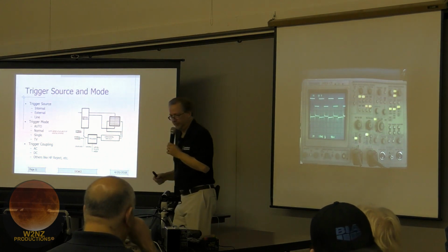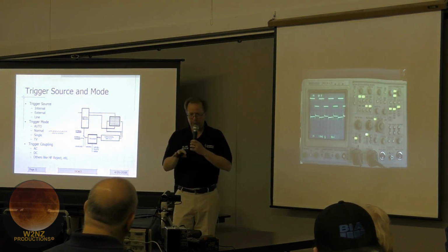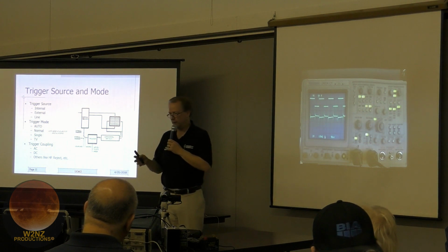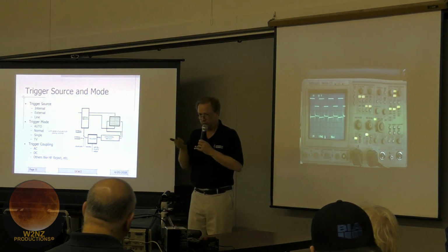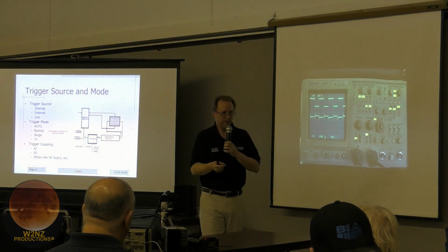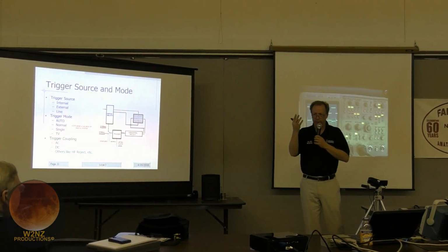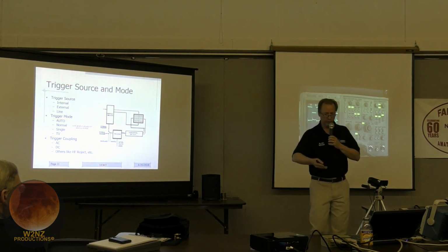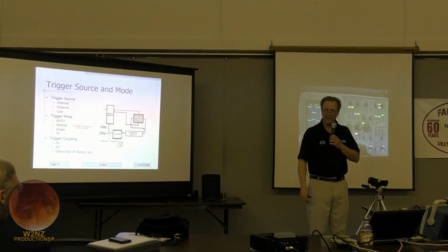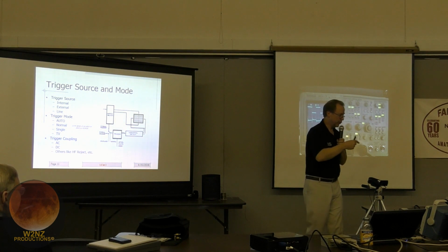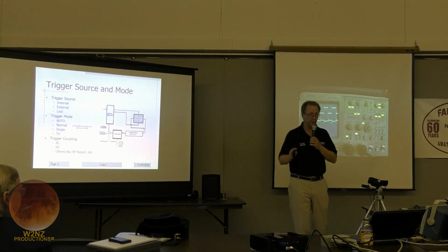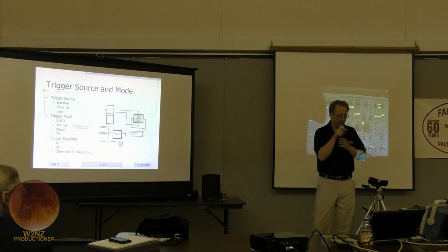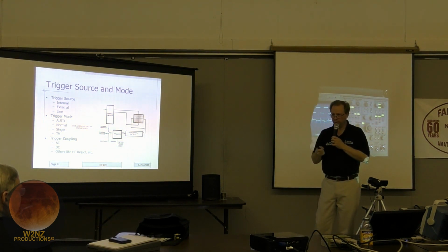I'll give you a little bit of a hint. For most Tektronix scopes, old analog scopes, a lot of these trigger controls are all kind of next to each other. They're typically these big lever switches. If you want to just get the scope running and have something displayed, take all those lever switches and bring them all to the top. That puts you in auto trigger, DC coupled, ready to go, it starts triggering, and you're good to go. So it's a good starting point. These old scopes don't have a reset button. You can't reboot them. That's kind of the auto set, if you will.